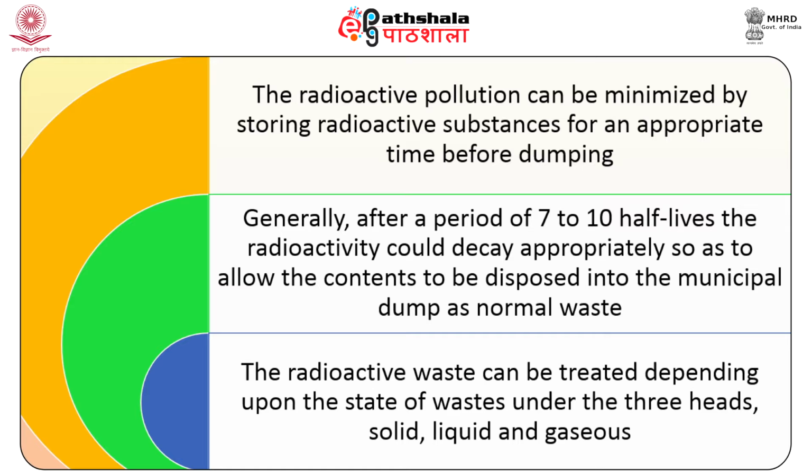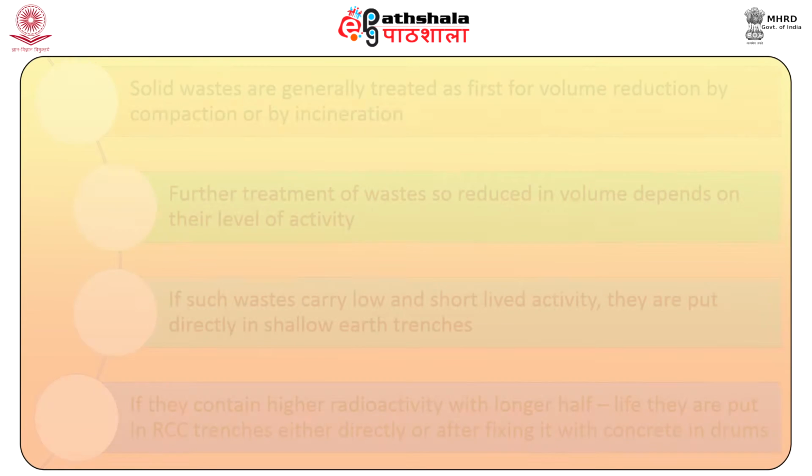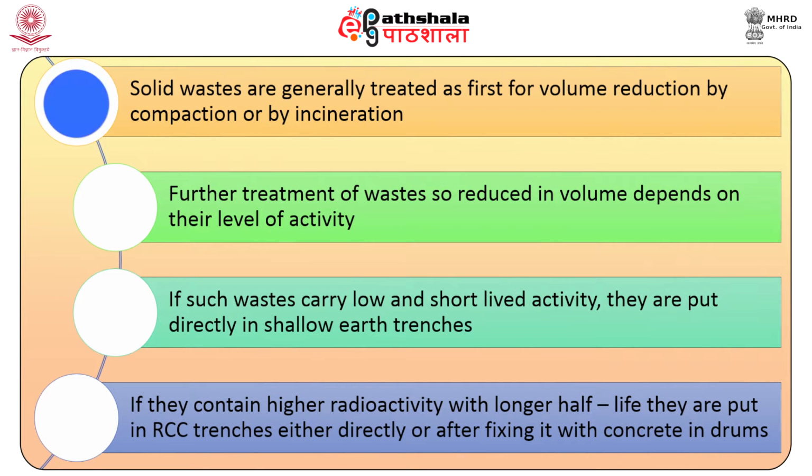The radioactive waste can be treated depending upon the state of waste under three heads: solid, liquid, and gaseous. Solid. Solid wastes are generally treated first for volume reduction by compaction or by incineration. Further treatment of wastes so reduced in volume depends on their level of activity. If such wastes carry low and short-lived activity, they are put directly in shallow earth trenches.